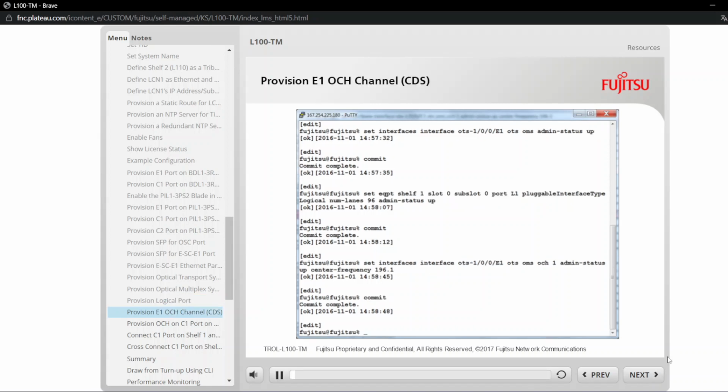The next 4 slides show the minimum provisioning required to connect the FlashWave CDS used in this example network through the 4x16 splitter coupler and the 1x9 WSS ROB blade. To do this, first assign an optical channel to the E1 on the 1x9 WSS ROB blade to support the FlashWave CDS service. This example shows the following.